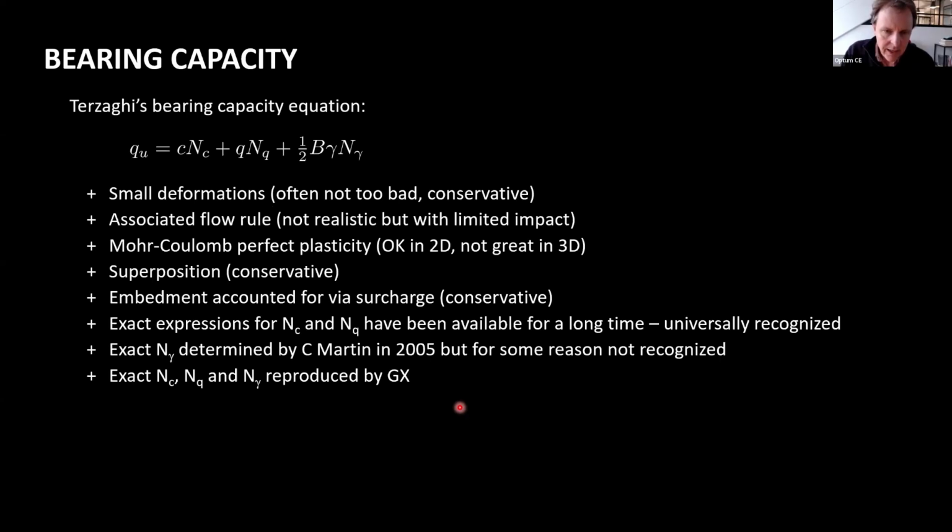But I can't really get started without mentioning Terzaghi's bearing capacity equation, at least not on the topic of bearing capacity. So of course that's been around for a long time, and it's very widely used. So there's three terms. The ultimate limit load is the sum of these three terms, something related to the cohesion, to surcharge, and to...